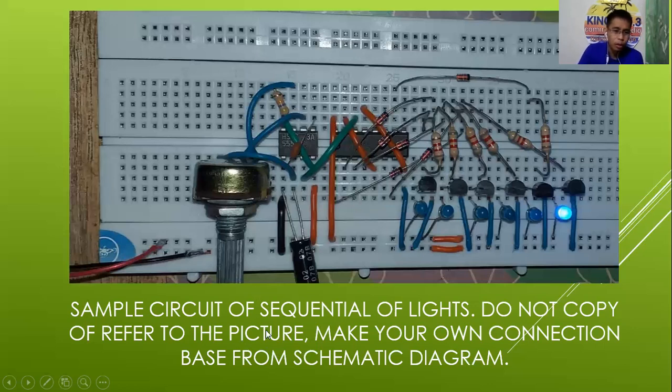So, let us review. Based from the schematic diagram, sabi doon, supplyan muna natin si IC. The timer IC, which is the 555 and the 4017. So, negative is pin 1. Tama ba? Okay, correct. Nasa negative. Si pin 13 and 8. So, okay. Pin 13 of the 4017. Okay, this is the pin 13. Kinonect ko siya sa pin 8. And then si pin 8 connected sa ground. Okay, correct.